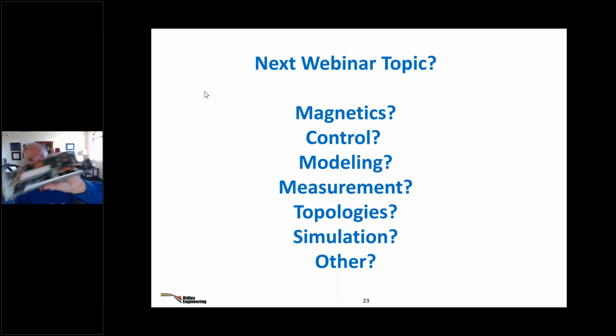There's a very similar application at 750 watts, where this has got 2 parallel transformers on the output. And it's my good old favorite converter, a 2-switch forward. Same kind of application, about 1 kilowatt. Same kind of efficiency. One of them is a lot easier to build than the other. The 2-switch forward interleaved is better than an LLC.